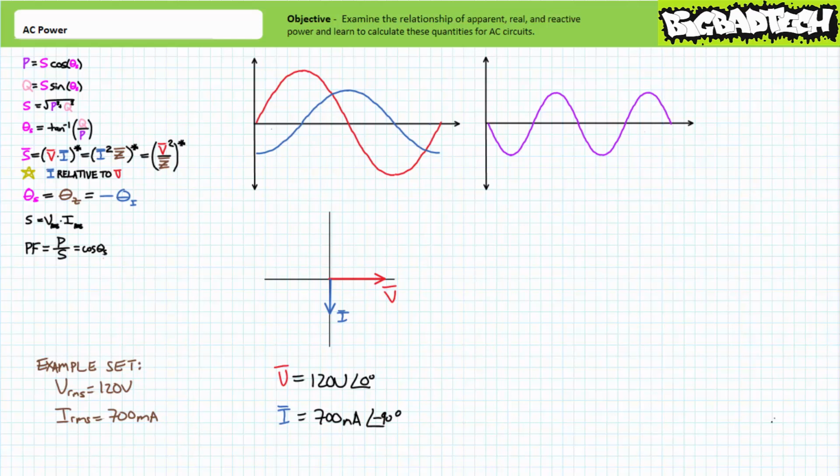Our earlier thought experiments led us to believe that given a phase shift of a full 90 degrees between current and voltage, we should anticipate a zero-centered power waveform with equal and opposite periods of positive and negative power. Given all of apparent power is now being directed towards the cyclical interchange of reactive power, we should expect none of it to be directed towards real power. Long story short, for occasions which current lags voltage by a full 90 degrees, real power is 0, and the absolute value of reactive power equals apparent power. Let's see if this is the case.